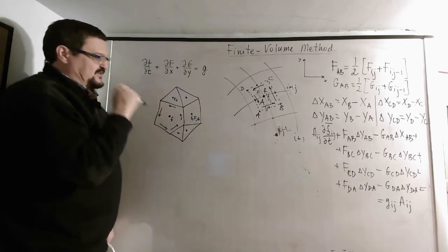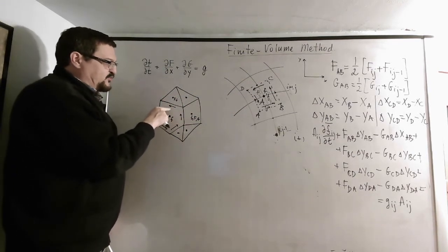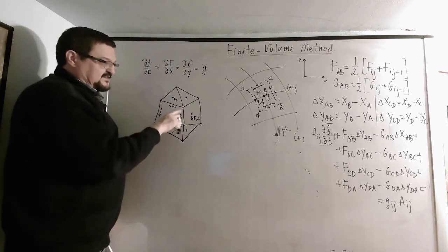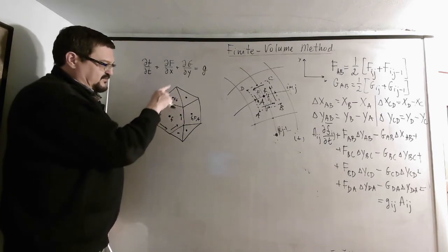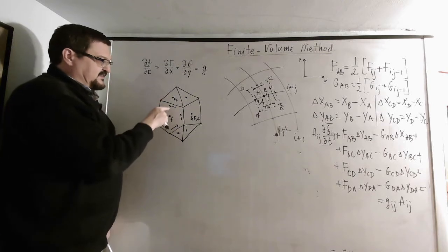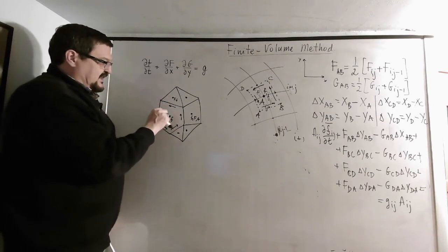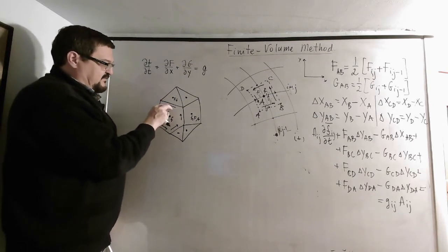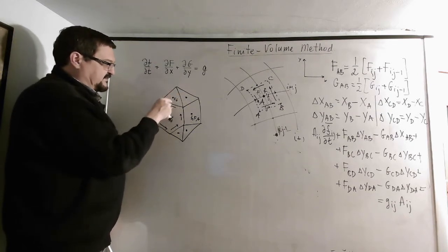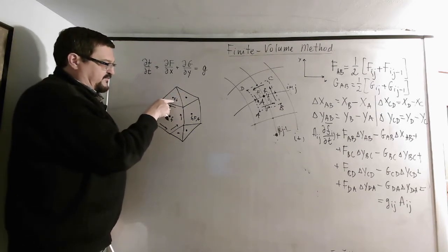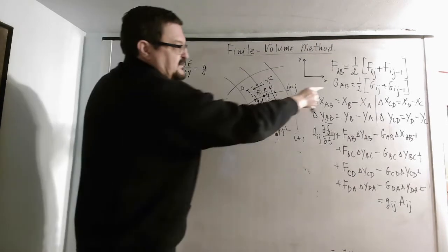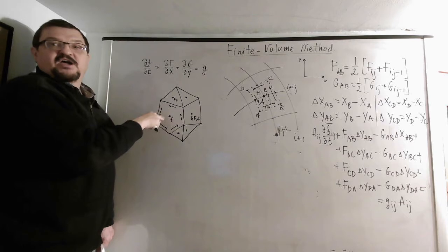So this is our cell. These are the values of f, and values of f and g computed in these cells. And for averaging, we need to come up with some scheme for how you compute this average when you have a very non-uniform grid. So we need maybe some area average, like the area of this cell and the area of this cell. When you compute the value of f or g along this edge, instead of 1/2 here, you use some area average.